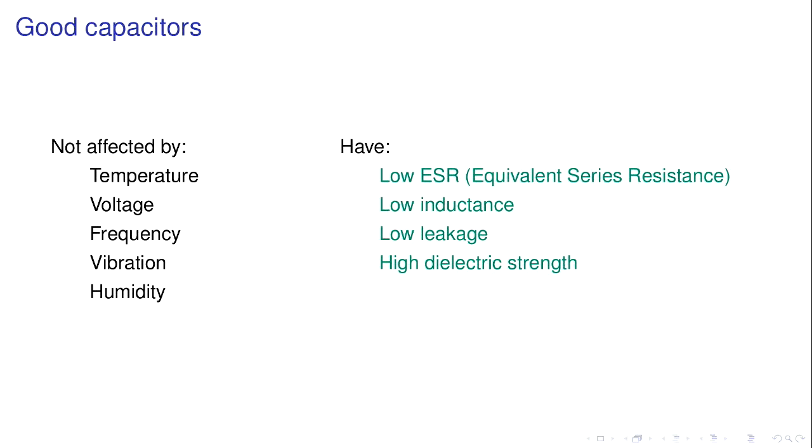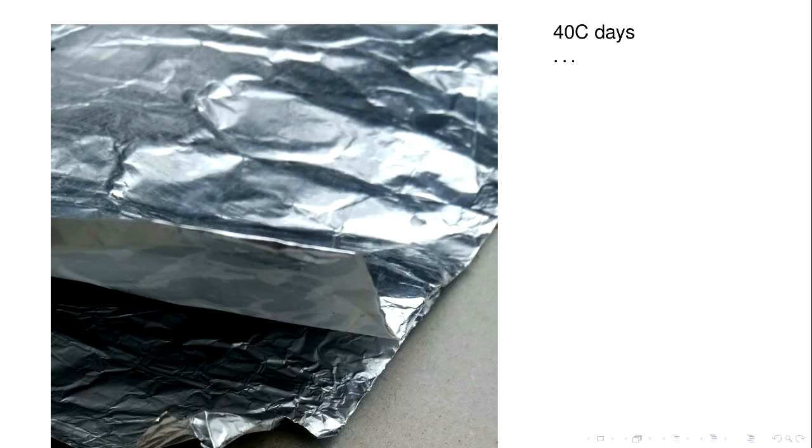The thing that this capacitor did was temperature. Remember those really hot days we had just before Christmas? That's what happened to my capacitor. It just delaminated. And now instead of a 50 picofarad capacitor, I've got a 20 picofarad capacitor, which is not what I wanted. So I've obviously got to do something better.